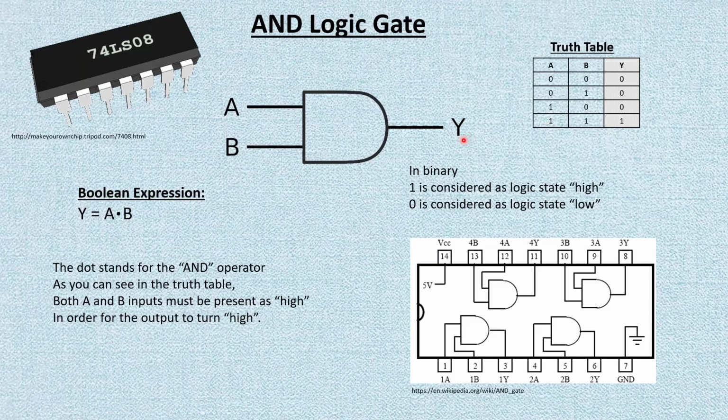And you can draw an equivalent logic circuit to each rung, or to the whole collection of rungs in the ladder logic for the PLCs. Sometimes you are going to be faced with a problem where you need to come up with a simplified Boolean expression, because when you design a system, each piece of equipment has to perform certain logic, and you can connect those in a very complex way.